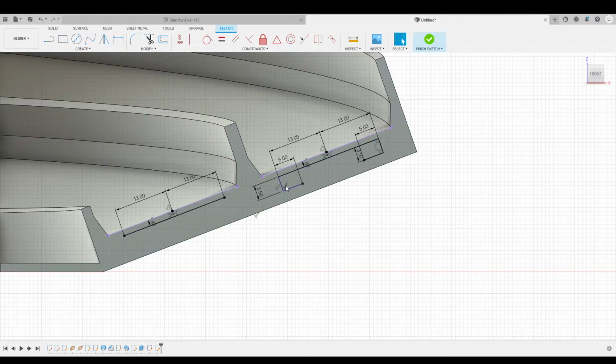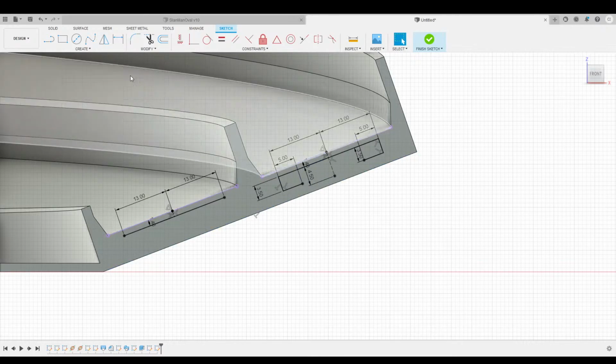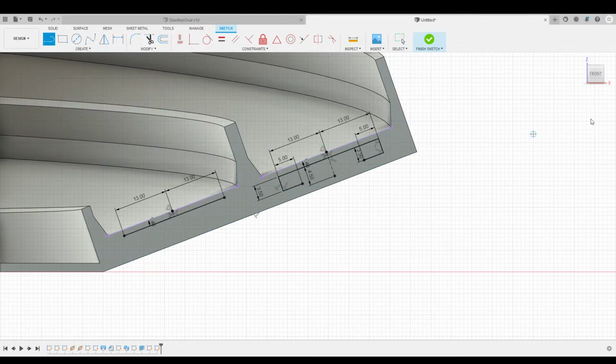And actually, the original reason I did the little V cut here, I don't know if Slam knows, but it was because my original connectors, when I would stuff them in, they would actually break apart the layer lines based on the way that I'd print it and how flat it was, and I'd get cracks down here, and it was really frustrating. So I added this, I think I just called it the stress relief. It makes it play less nicely with the actual Hot Wheels connectors, but you can kind of just fit them in there. They still fit in there and work.